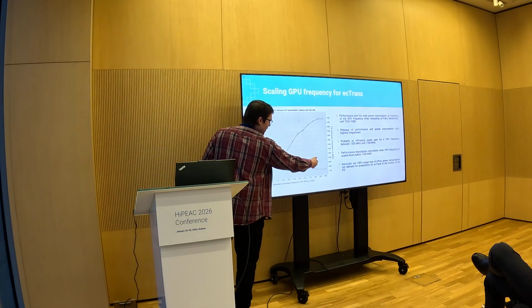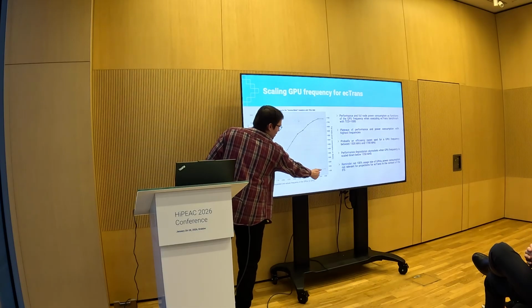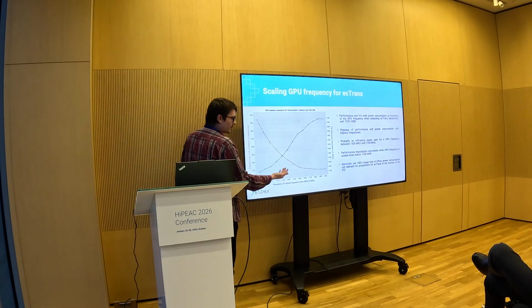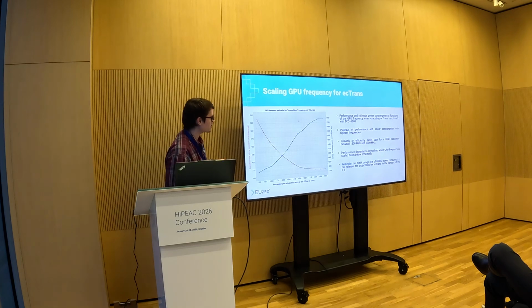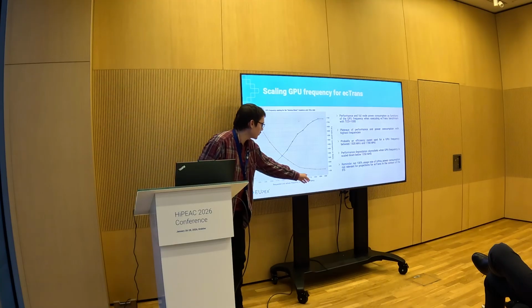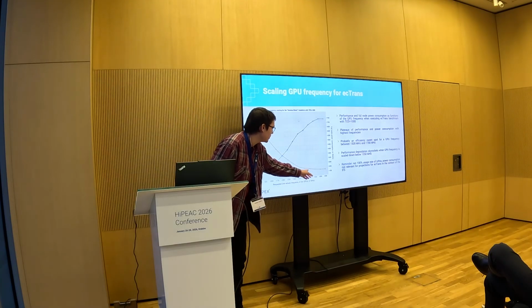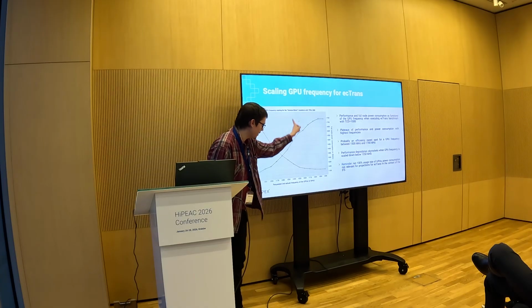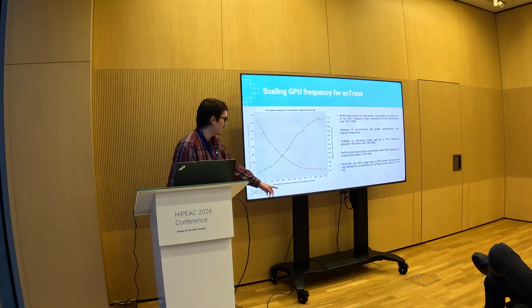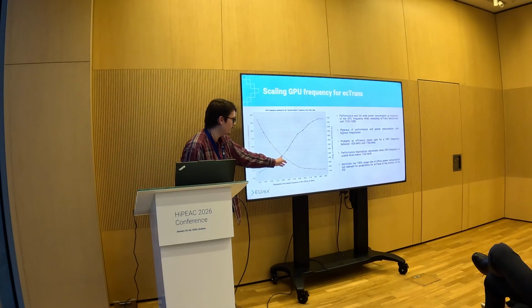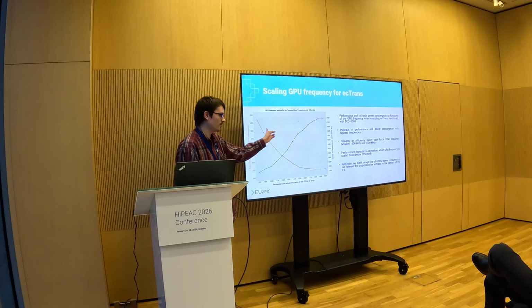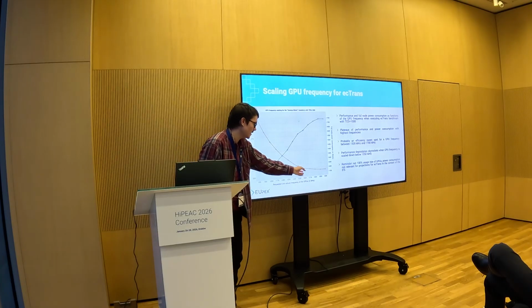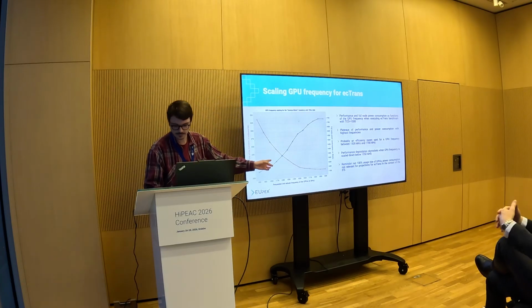If you are not sustaining a full GPU load, you might reach higher frequencies, but under a heavy load, the maximum reachable frequencies will be lower. One thing we can also notice is that there is kind of a sweet spot for efficiency, because performances are quite stable even with lower frequencies when the power consumption decreases. So here there might be an efficiency sweet spot. And if we scale down the frequency too much, the performance degradation just skyrockets. So we should not do that if we are interested in maintaining a high level of performance.